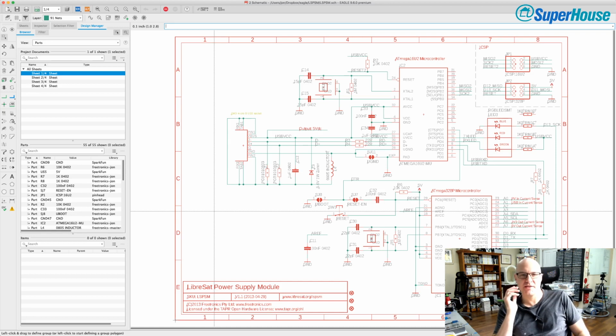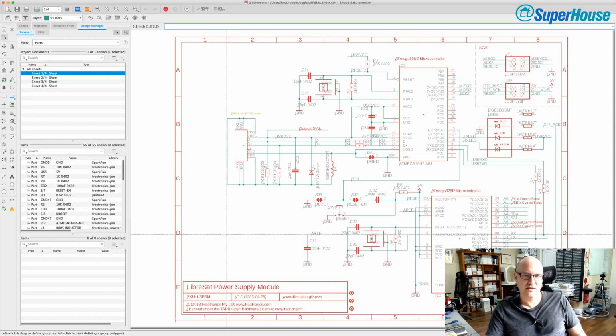So what I've been talking about so far is measuring power for AC, so like typical household power supply. That's where you use either a CT or a Hall effect sensor or something like that. The other situation is where you need to measure power at a much lower level typically, and it's DC. And that's usually done using something like a voltage drop across a very low value resistor.